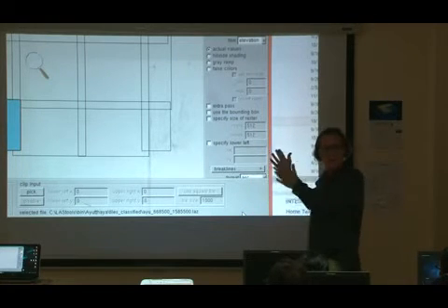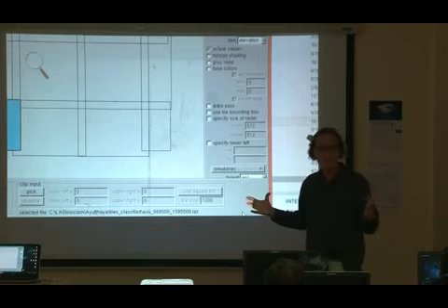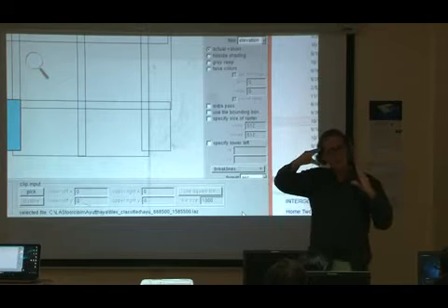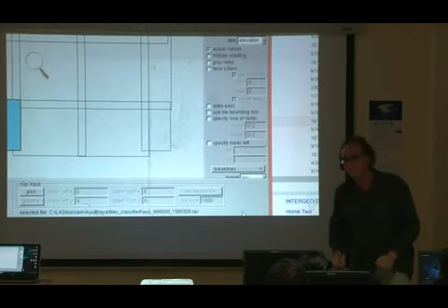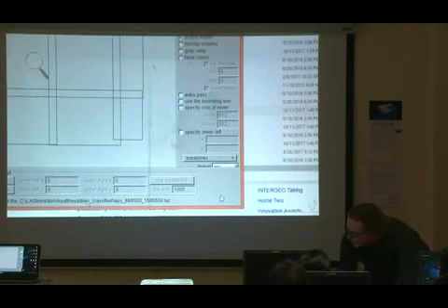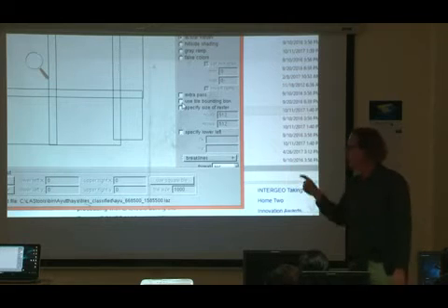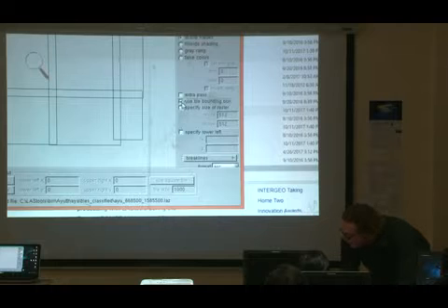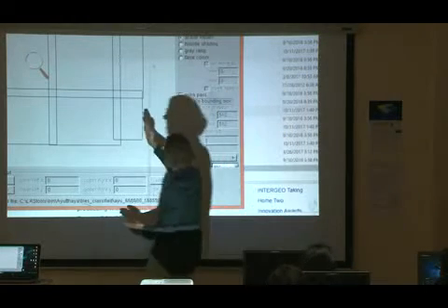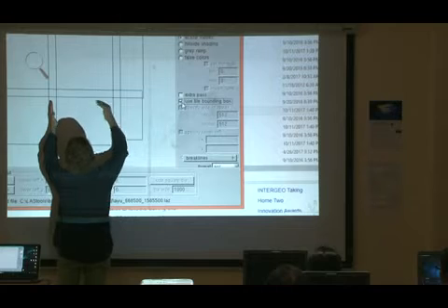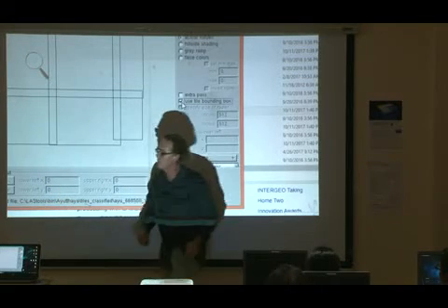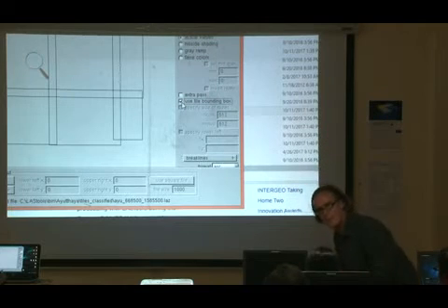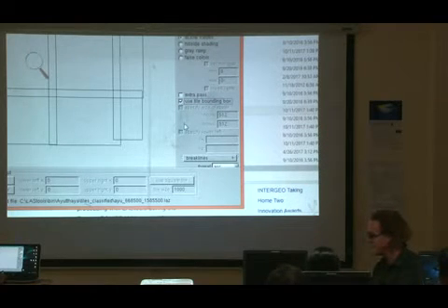Use tile bounding box as a gigantic 500 by 500 meter cookie cutter. Because now I'm cutting out only the center 500 by 500 meters to actually compute the raster. Raster is a grid. Grid is an image: elevation, grid, elevation, raster. But only the center, from here to here only, and to here. Only the center 500 by 500 meters. And I do this everywhere, and then I should have nicely, seamlessly, without distortion, DTMs that fit together.